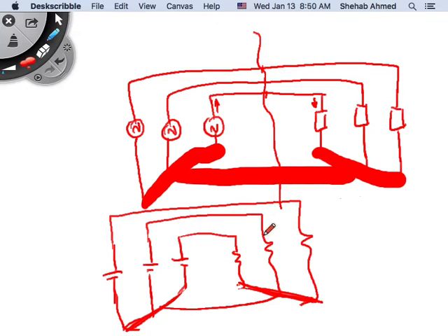But you can come and tell me, okay, but you put a thick cable here, but this thick cable is not really a thick cable, because from Kirchhoff's current law, what will happen to current at this node? All the currents from this load and this load and this load will be summed up at this node, and then they will flow into this conductor, correct? So if this was 1 amp angle 0, 1 amp angle 0, 1 amp angle 0, then what is the current flowing in this conductor?